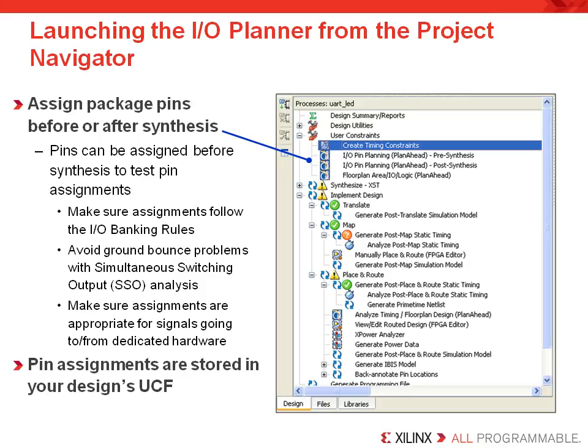The I/O Planner checks that your pin assignments follow the I/O banking rules. These banking rules must be followed since each I/O bank is powered by a VREF and VCCO pin. The VREF powers all the input pins in the entire I/O bank, and since each input pin requires a different power voltage, this rule assures that all the input I/O standards have the same VREF. Likewise, each output pin in a bank shares the same VCCO, and the banking rules require this voltage to be compatible. There is also a noise analysis utility incorporated with the I/O Planner.